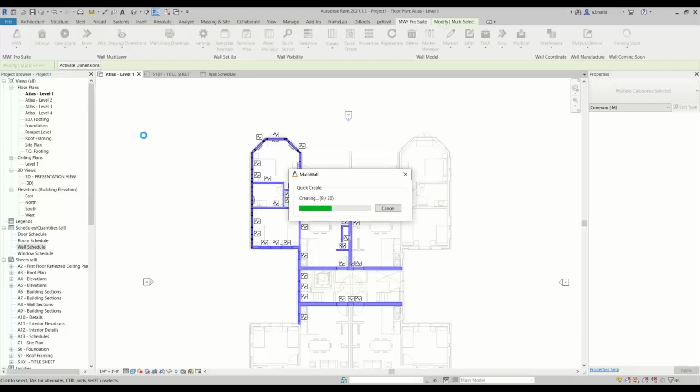I know for steel, there are a lot more intricacies for templates, so you can definitely create walls, like the first pass, you can just draw the walls like how we just did. But if, say, in like this area, maybe you need to have a specific, more beefed up template, you can always just select those 3 walls, replace them with the wall that's going to be using that template that has the same stud thickness or structural layer thickness, and you should be good to go. You can just go ahead and do quick create again after you replace those walls, and you should be okay, right?